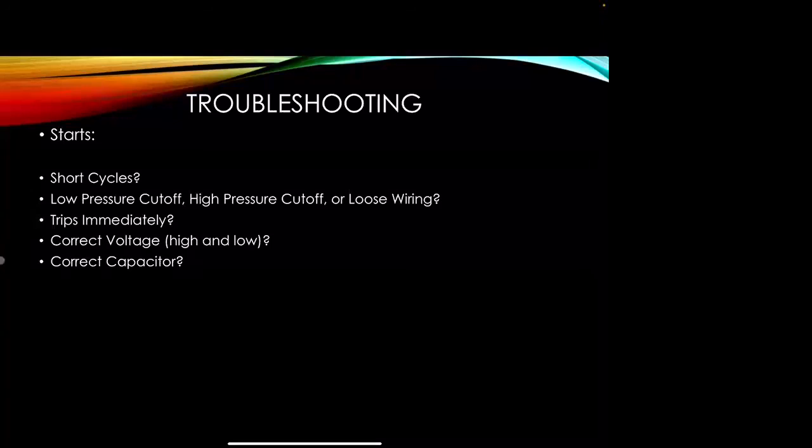If you're ever questioning that right there, you can use an Emerson app and put in the model number of that compressor and it will give you all the information on it. Or you can actually go to your CE app or Service Tech app and type in the compressor model number, serial number, and it will give you that information as well.